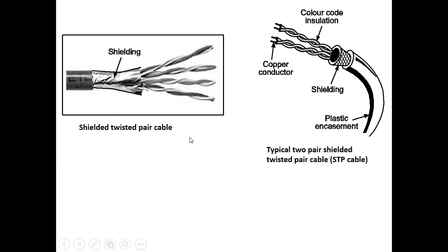Such shielded twisted pair cables are used in environments where electromagnetic interference or RF interference sources are more, like industrial areas where there are motors, brushes, transformers, electric switching, high current switching, welding, arc lights, such type of heavy currents and heavy electromagnetic sources which are unwanted and act as noise. That's why this STP type of cable is normally used in such an industrial environment.